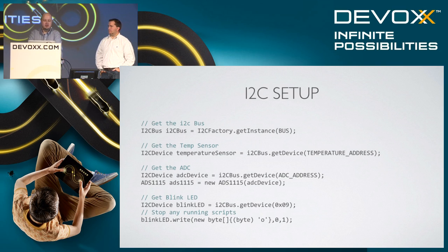So the nice thing is we're using some little I2C LEDs here, which actually have an Arduino-based chip in the LED. And so it does all of the hard work for making the LED work, and we just send it commands over the I2C bus saying, go to this color. Or you can even say, animate to this color, or create an animation script with a number of different colors. And they have some built-in ones for things like lightning and thunderstorms and other fun things, or sirens, like police, flashing blue sirens and stuff.